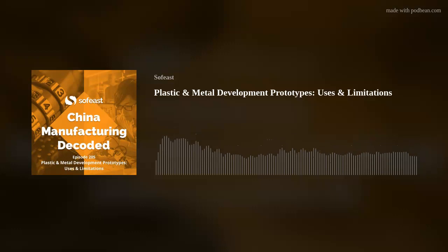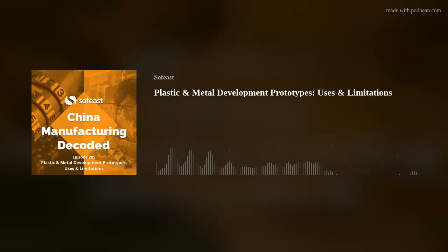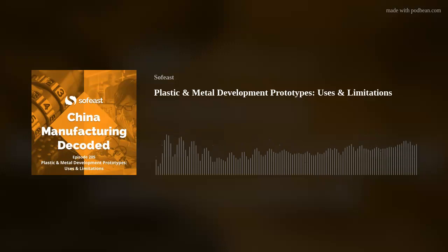Now, if you're looking at a simple product, for sure, you can go CNC machining. But again, you're looking at the limitations of CNC machining versus a cast product. You've got the setup cost. For a one-off component on a CNC machine, it's not as cheap as a 3D printing process. You've got material limitations with respect to what you can use, and will it be the same as your high pressure die casting, for example? You've got to take that into consideration.